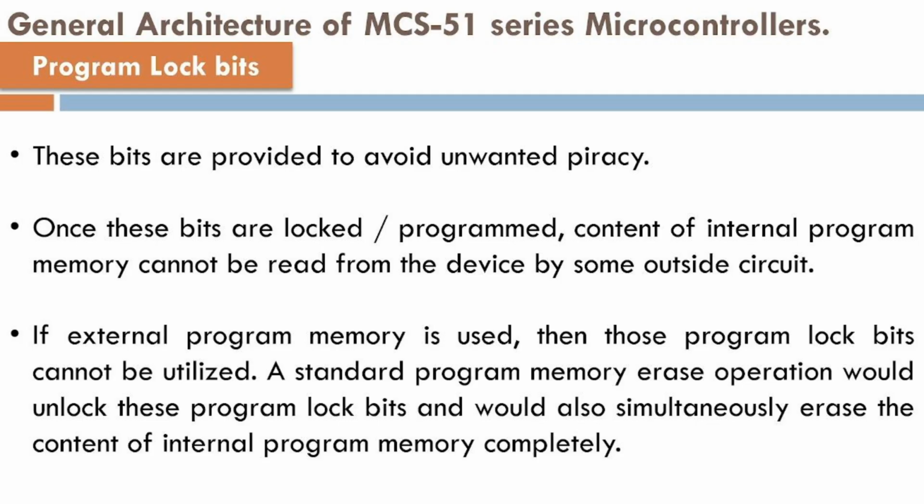The only way to remove the lock is through a standard program memory erase operation, which unlocks the bits but also simultaneously erases the content of the internal program memory completely.